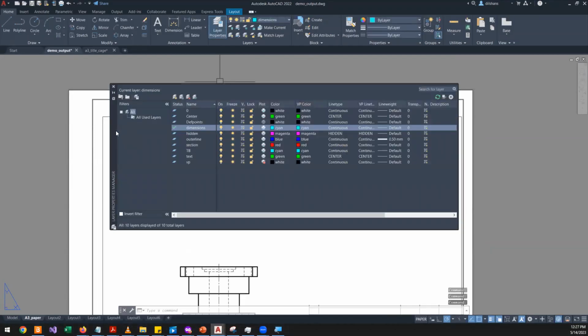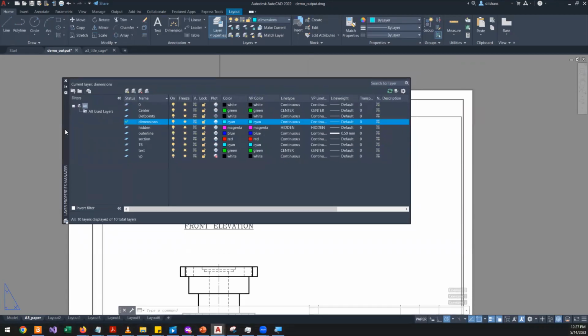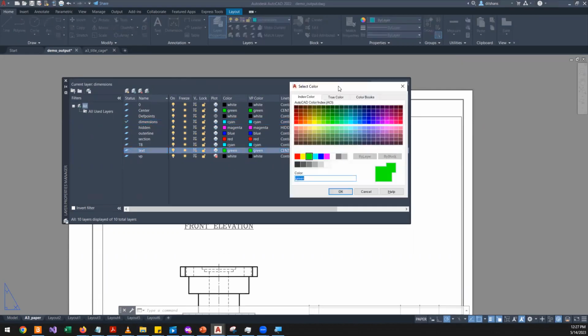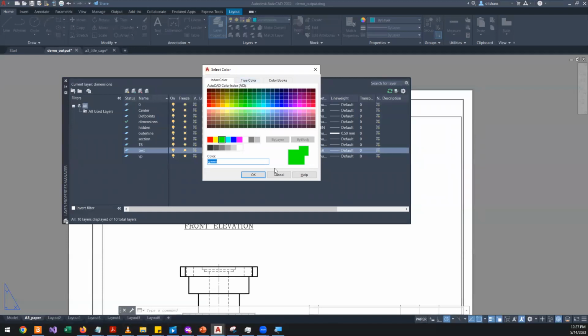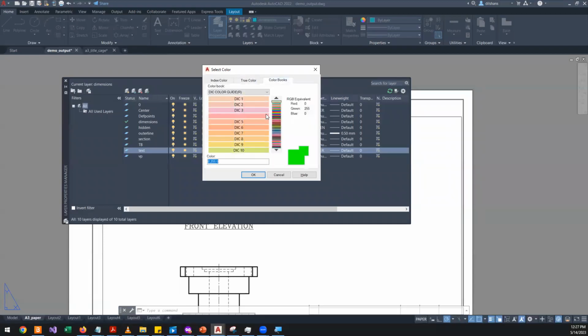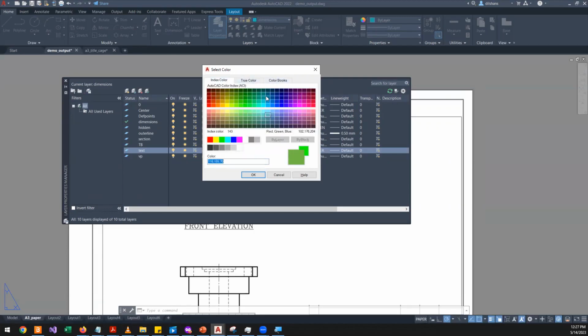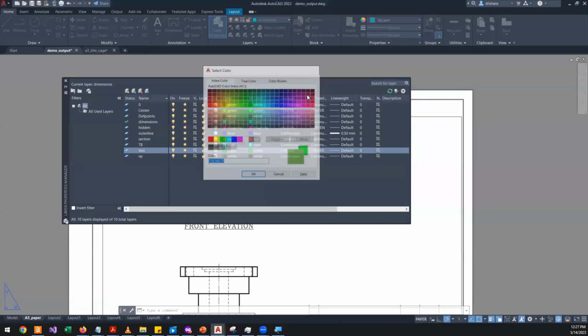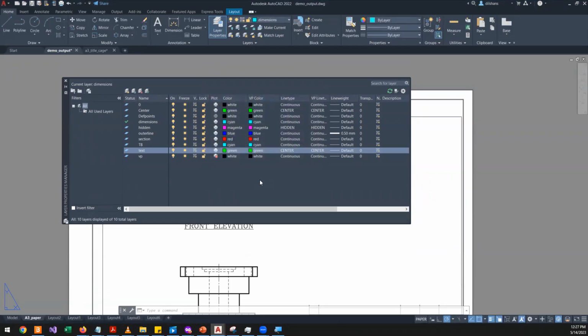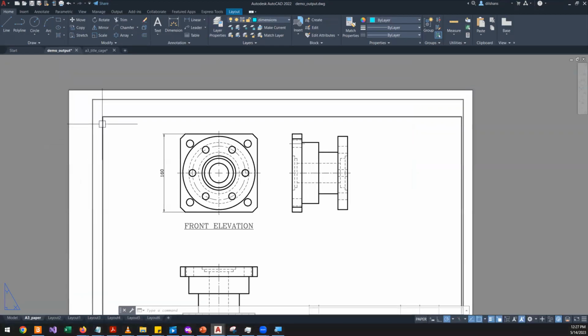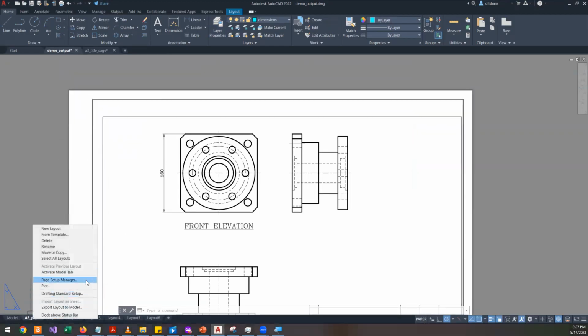When you create layers, like in the object properties, like I told you, when you create layers you should use the index colors. So these colors, not like true colors, color book or whatever that was. I told you to stay away from the true colors, color book, and use these index colors for your layer, right? Now I will explain why you want to use those.